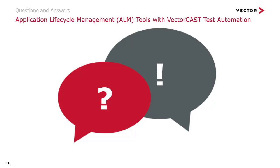So you're in a particular test environment, you add 2 test cases, and associate those 2 requirements. The impact analysis within VectorCAST will say, look, those 2 test cases haven't been run yet. You need to run those 2, and those are the only 2 that need to be run because those are the only 2 new ones that you have. We'll also take into account any other source code changes that occur, and we'll rerun any test vectors that have to be rerun because of those as well.